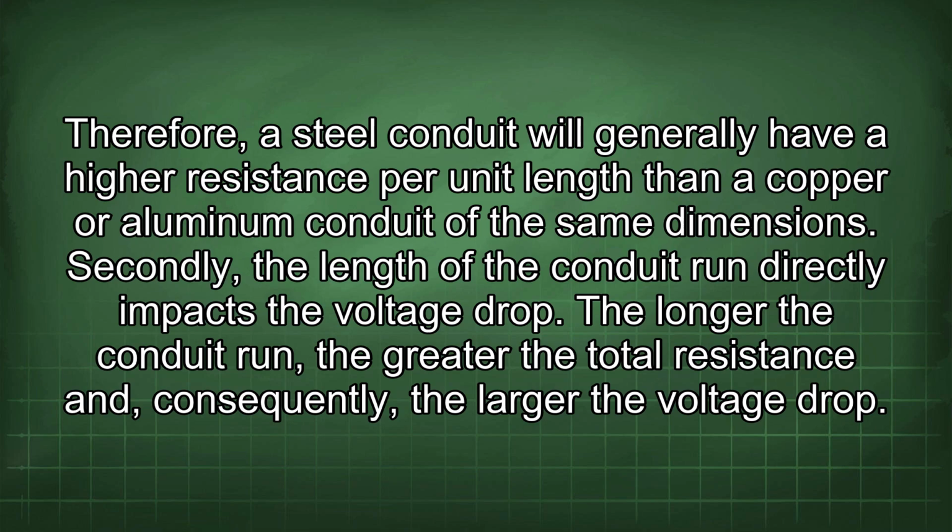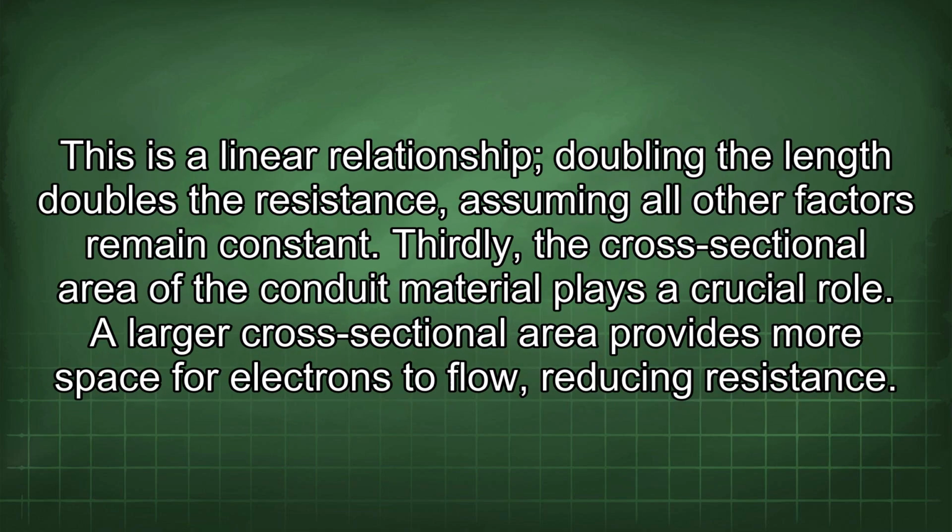Secondly, the length of the conduit run directly impacts the voltage drop. The longer the conduit run, the greater the total resistance and, consequently, the larger the voltage drop. This is a linear relationship. Doubling the length doubles the resistance, assuming all other factors remain constant.